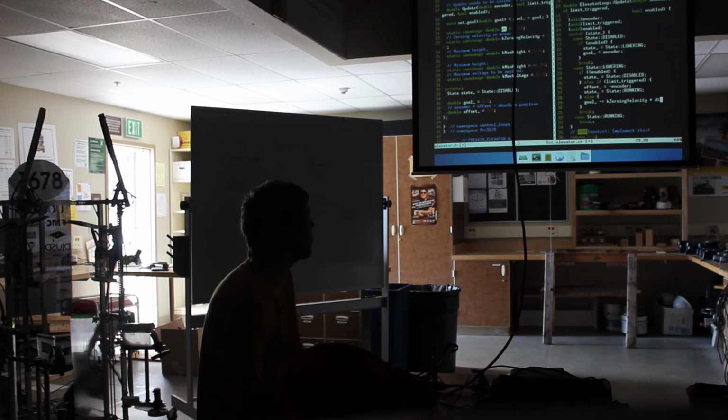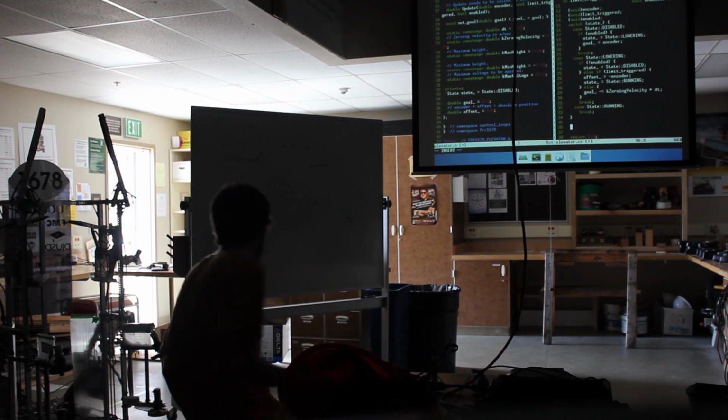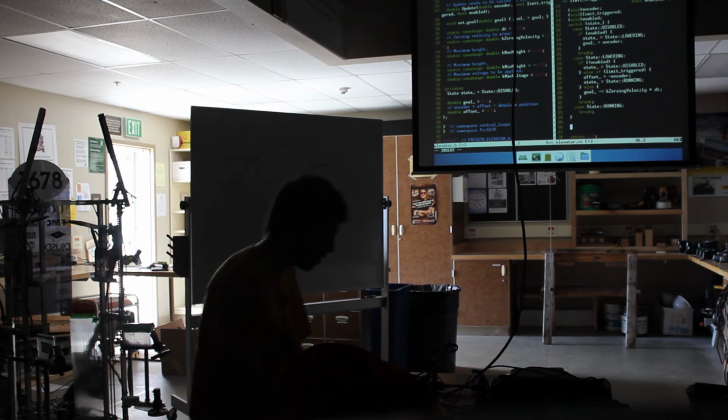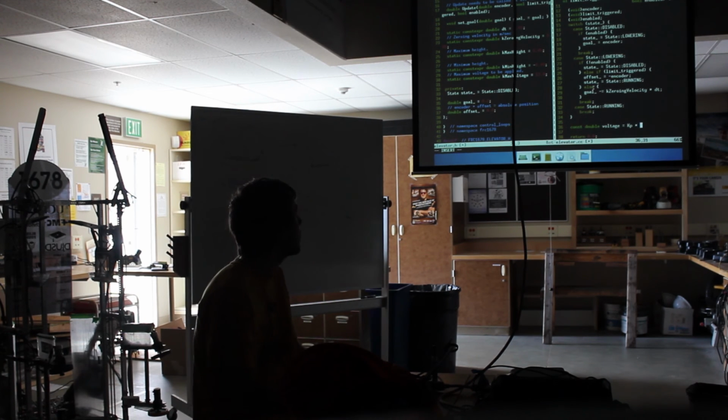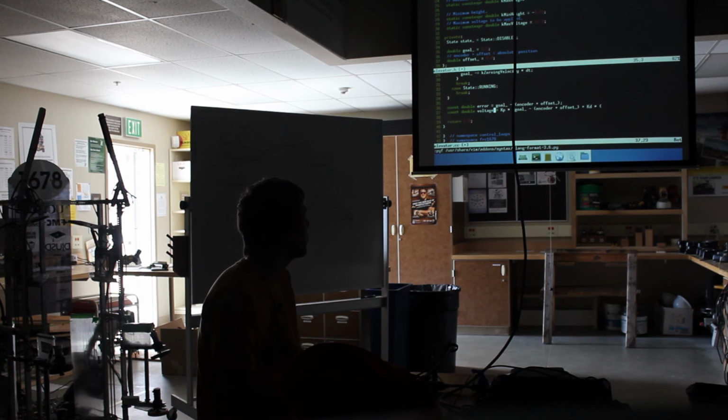So now we have something that's going to move through the states, and we need to implement it. We want to implement a little PID loop here. The basic idea is some proportional constant times our error. So now we need to compute a derivative. We should probably save an error and a last error. Question: if this is a velocity PID, why are we doing position PID? Oh, for lowering?